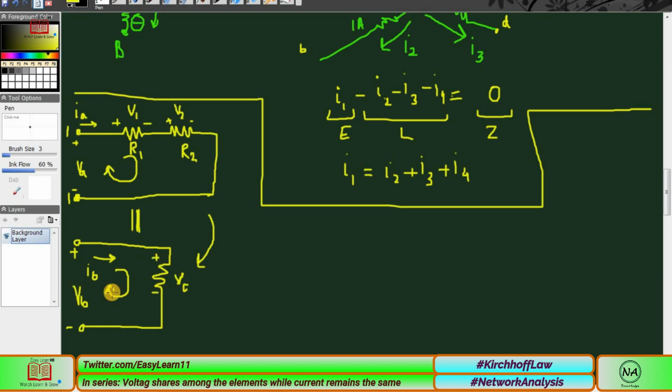Actually the whole VB is attached to this one, there is no division further, so we can also write VB here, because overall VB equals VC, because whatever the voltage at the terminals is coming directly across this resistance. There are no other elements connected, but just for understanding, I'm writing it here. Okay, now it is time we wish to determine the conditions under which these two networks look like and behave in a similar way. The two networks are said to be equivalent at the pair of terminals if the voltage-current relationship is the same, meaning VA must equal VB and IA equals IB, then we will call that these two networks behave in a similar way.